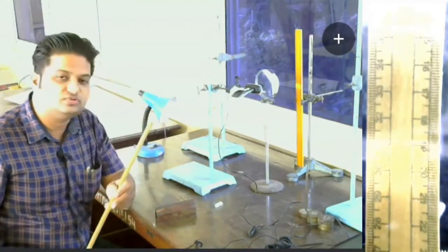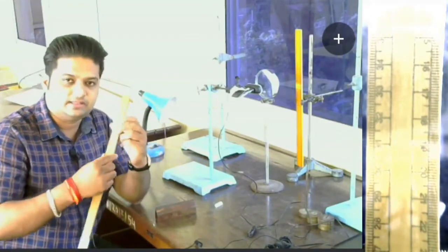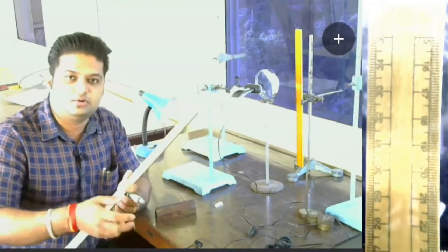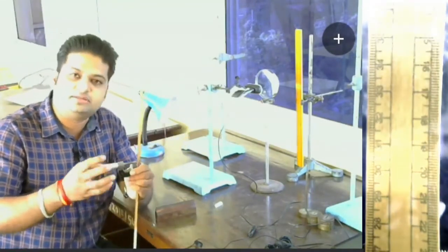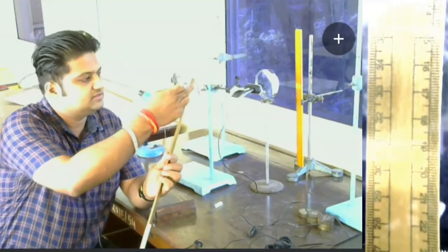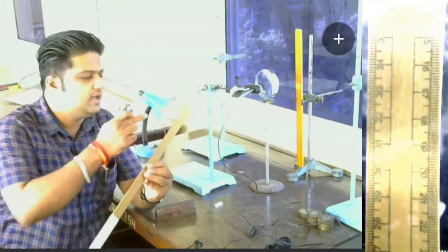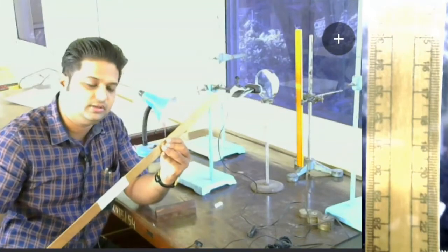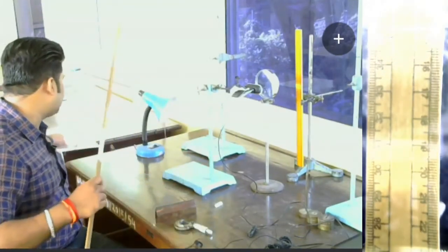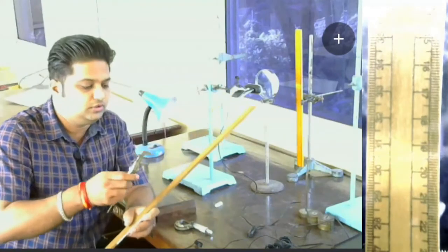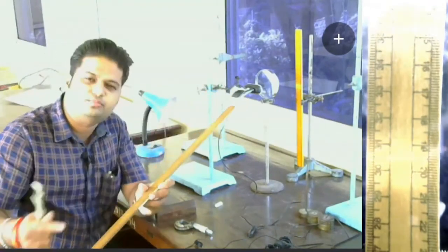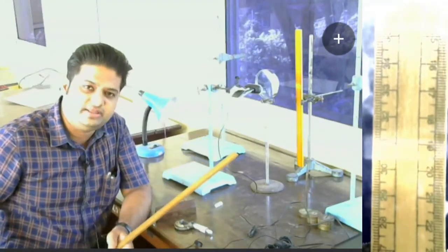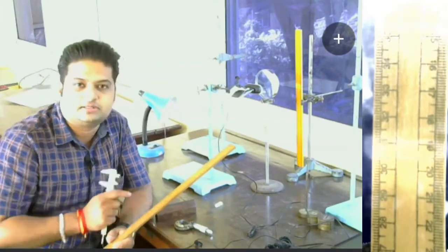But before that we have to do certain calculations, for example the depth and the breadth, which we will do now. We will use the micrometer screw gauge to measure the depth, the thickness of this ruler, at 3 different points. Maybe we can take the reading here, then here, and then here. Then we will also use the vernier caliper to find the breadth of this beam, again at 3 different points. Any 3 random points, it's up to you. We will do that, and then we will start our experiments.